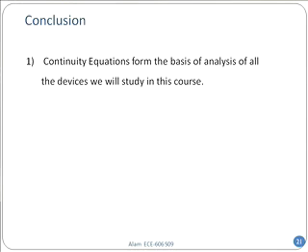What I began discussing today is that the continuity equation is a basis for semiconductor device analysis, because this was like a capstone for all the 5 equations that you needed to think about. These are actually done. And generally, the continuity equation is always true. You should be able to take any device, any problem, and without consulting any textbook, be able to write the continuity equation, be it for phonons, photons, electrons, whatever it is.